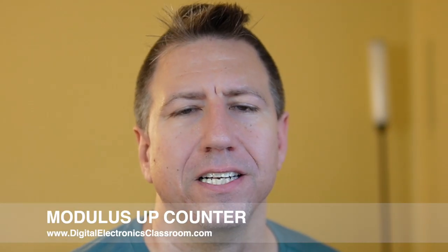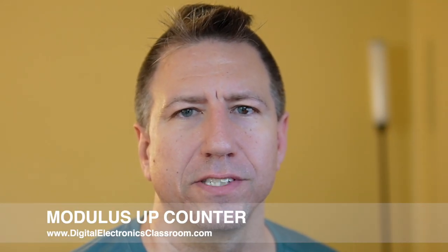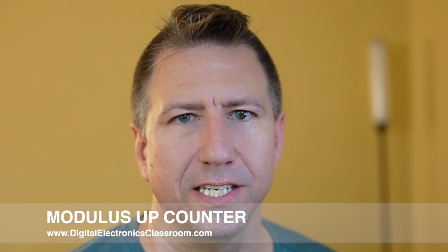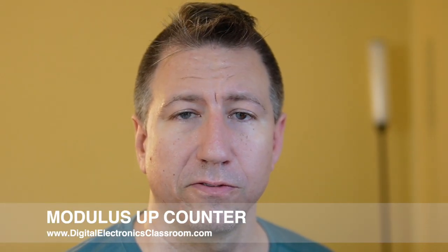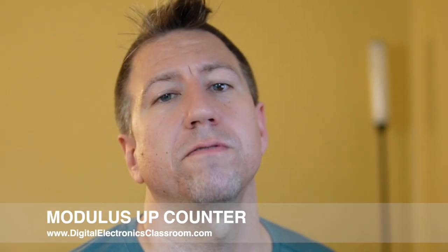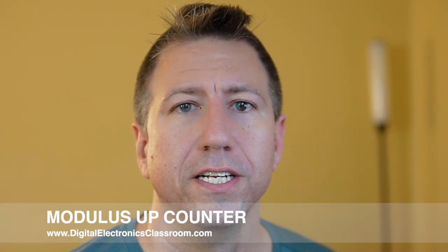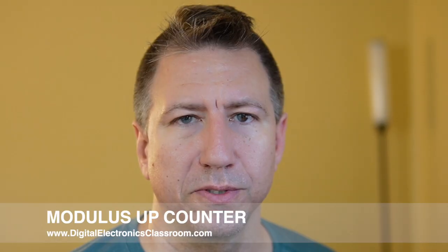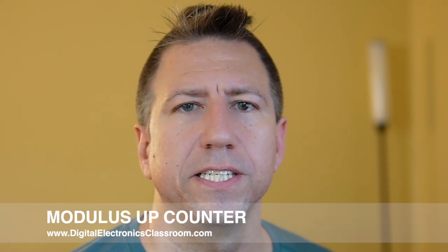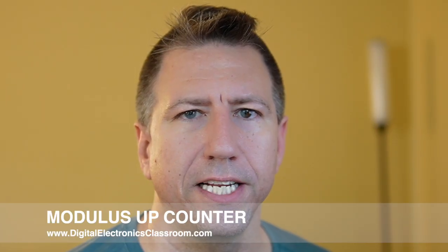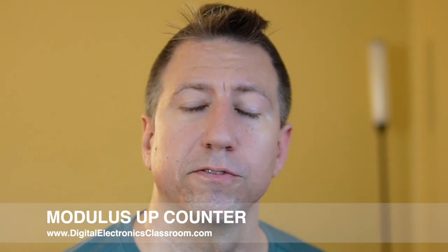In this video we're going to look at modulus counting. Now, modulus counting is a count in which we don't go through all the states that are possible in our flip-flop system. So for instance, if we had 4 flip-flops in our counter, that means that we would have 16 possible states, 0 through 15 or F. But if we didn't want to count between 0 and 15, we have to do something to our circuit so that we can count through a different range.